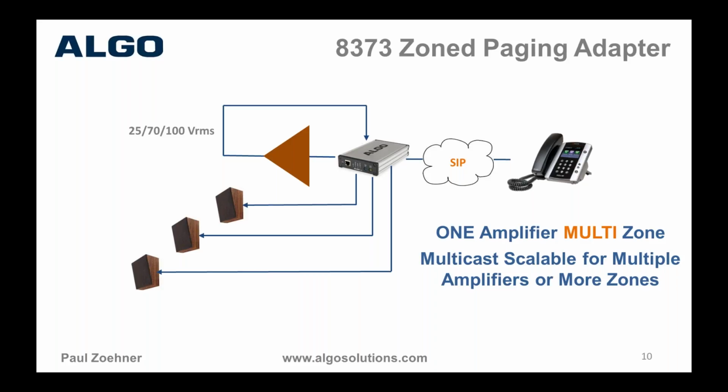You can have the zoning based on after a SIP call is made, the key presses that come from the phone to determine the zone, or the zoning could be based on the multicast address that is received by the device. And again, scalable, not just for multiple amplifiers, but also if you have a single amplifier that has more than 3 zones behind it, then these devices can be multicast scaled, so you can deal with scenarios where they have 6 zones, 9 zones, 12 zones, or more.